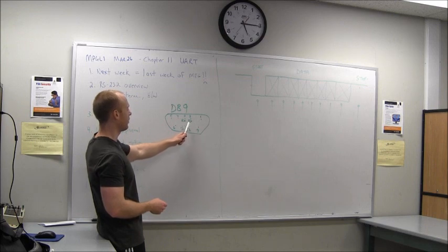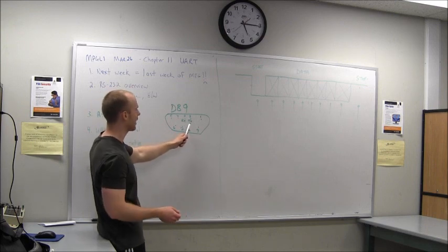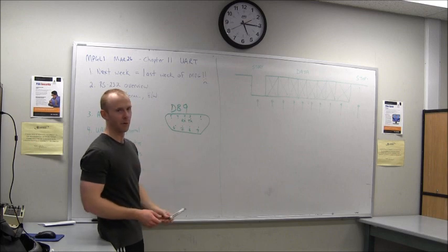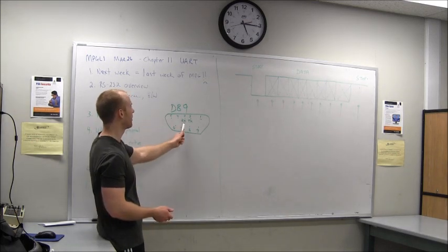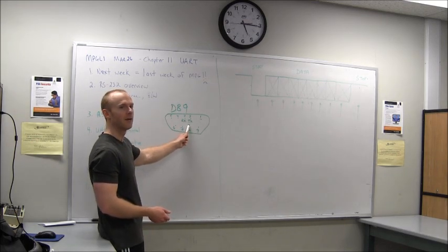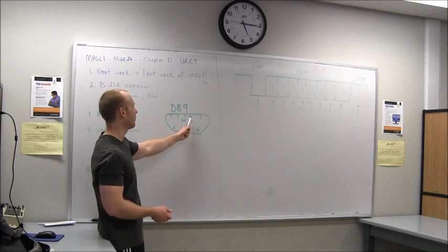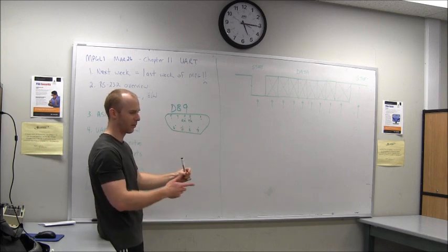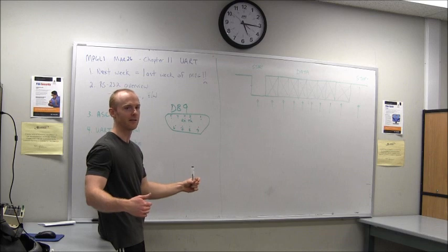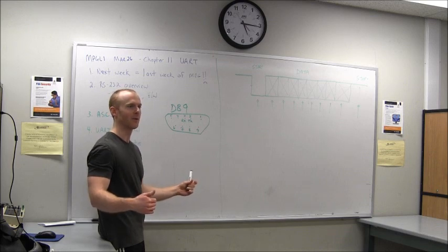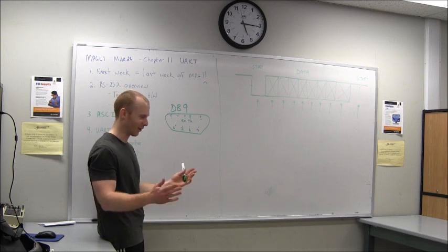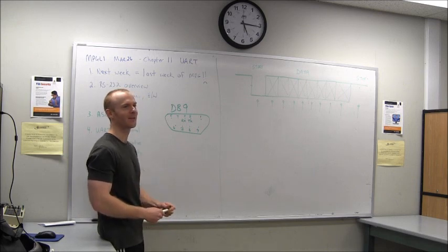With a regular straight-through cable, TX will come through TX on the other one, but there's something called a null modem cable or a crossover cable, where these two are swapped in the cable. That means that pin 2 on one end routes to pin 3 on the other end. And the worst part about null modem cables is that most of them look exactly like the other ones. So you go to your office and you'll be like, why isn't my serial connection working?